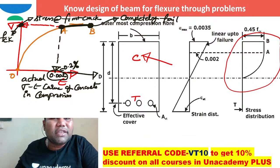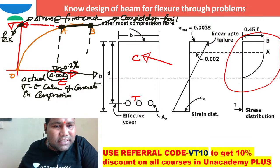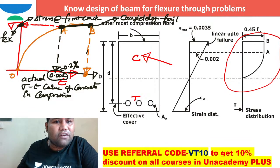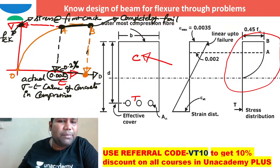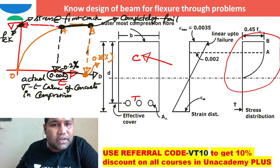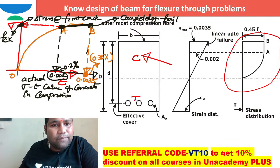And at what strain does the complete failure in concrete take place in axial compression? This is also a standard one. That is nothing but the maximum strain, the ultimate strain of concrete at failure. What is the ultimate strain of concrete at failure? This is 0.35 percentage strain. So in other words, I can write it as 0.0035, right?